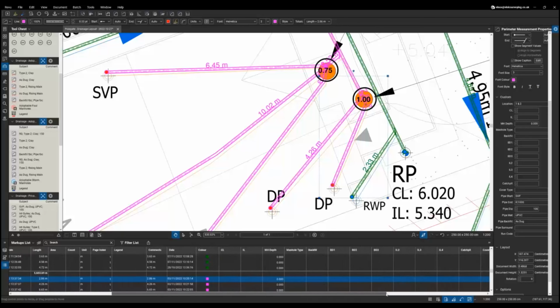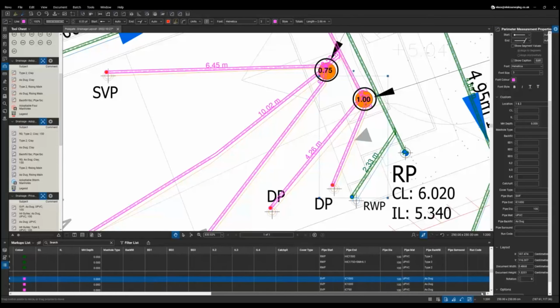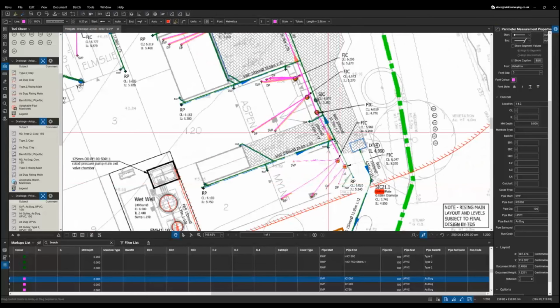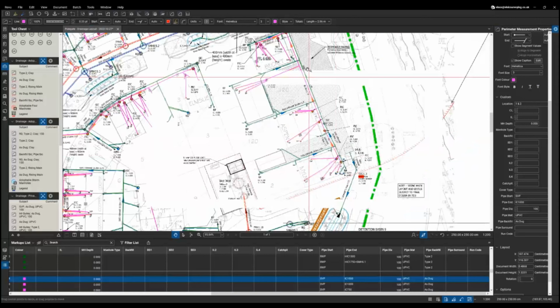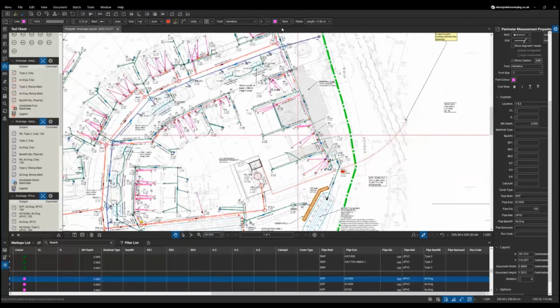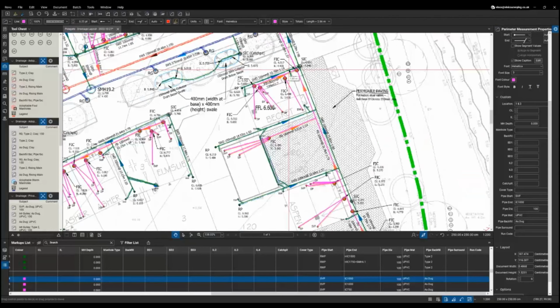And over here is where all the details are. So I said that the saw vent pipe bit was filled out automatically. I have to fill out my end detail, so I know that's an inspection chamber 1 meter deep. I see 1,000. If it was in a driveway, the inspection chamber, then that would be an HIC, hard inspection chamber. You'll see why I've done that in a minute.